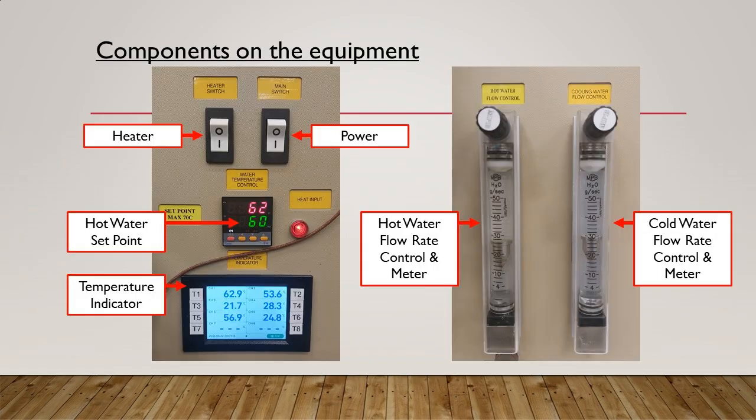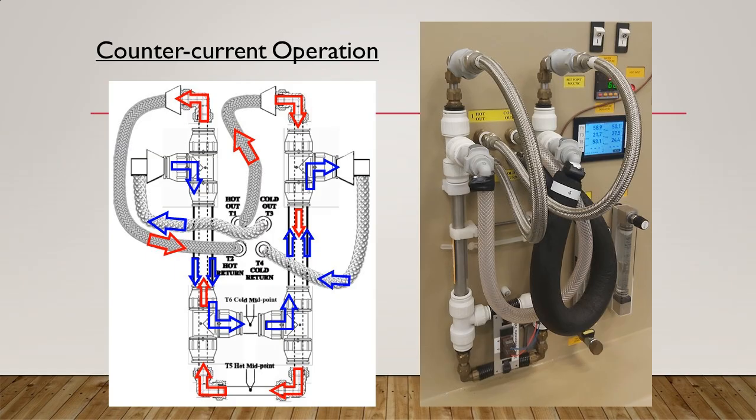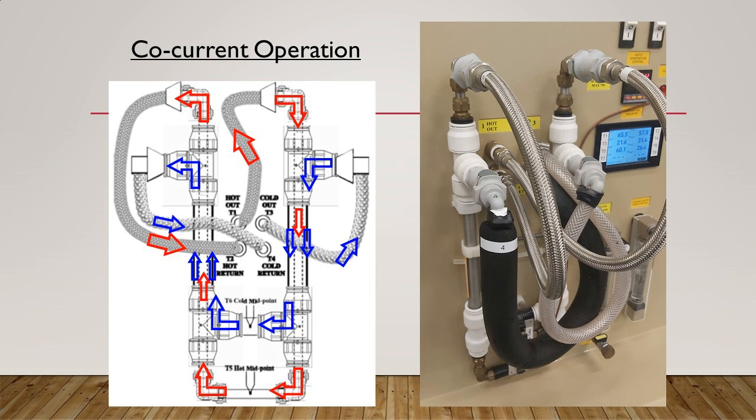Before starting the experiment, familiarize yourself with the equipment. Identify the mains water supply, hot and cold water flow control valves, and the hot and cold water flow rate meters, ensuring that you understand the flow directions of the hot and cold water streams.